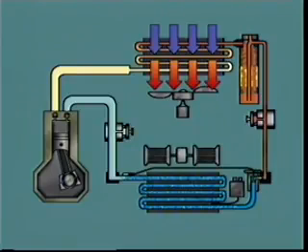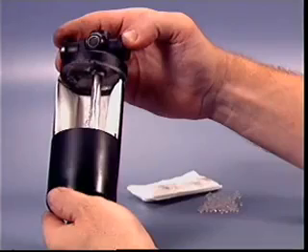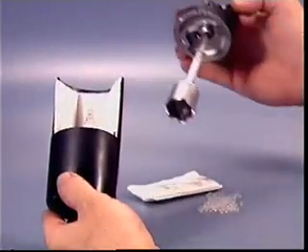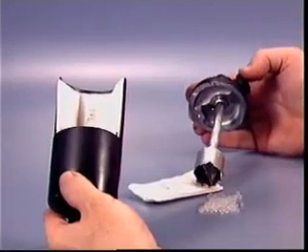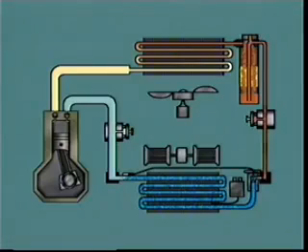The reduction in temperature causes the refrigerant vapor to condense and turn into a liquid which flows to the receiver dryer. The receiver dryer acts as a storage volume for liquid refrigerant and also contains a filter and desiccant or drying material. The liquid refrigerant must pass through the filter and desiccant to reach the pickup tube where the refrigerant can flow on to the TX valve.